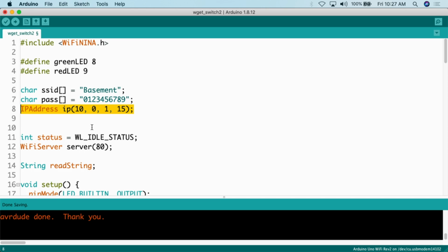Whenever you're dealing with these Arduino Uno projects, do remember they can pull a DHCP address, and they pull a DHCP address quite fine. The problem is then you're not really sure where to send the commands. So if you don't want to rip out the little hair you have left, I would argue for a lot of these projects, especially in the testing phase, do make sure you put in a manual IP address so that you know where your little device is on the network.